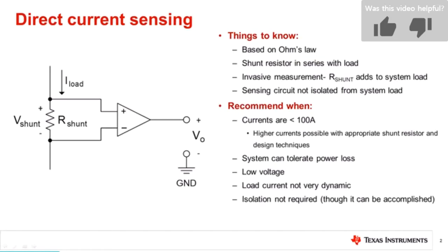The sense voltage across the shunt resistor is small, typically in the millivolt range, so it must be amplified and signal conditioned to be processed by systems downstream of the current sensing circuits. I will review the pros and cons of various implementations so that you can choose the best method for your application. Before we can look at the various circuit options, I need to introduce some basic concepts that will help you better understand the application.